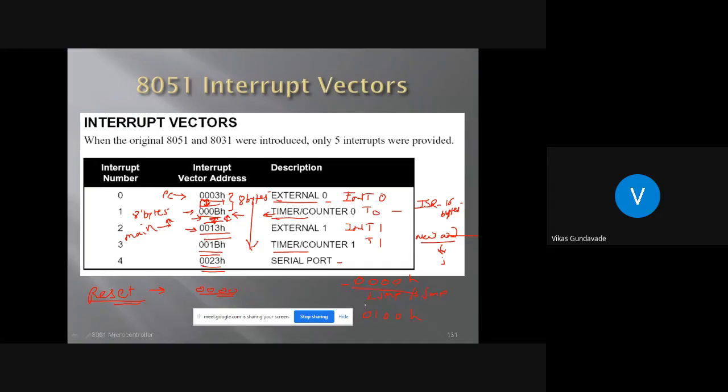So from this initial location, we need to jump to this 0100 location or the next location where the scratch pad is available, and then write the program for any practical embedded system design. Everyone understood it? So for Keil, here we are writing the program with the initiation of 000H, but practically it will not be possible because if the interrupt gets generated, the ISRs are available at these specific vector locations. Everyone understood it?